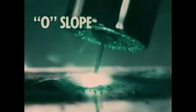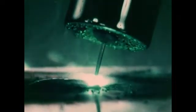Without control over the amount of current, the clearing of the short circuit as the wire touches the work is violent. An intense spatter occurs. The extreme heat is causing the remaining electrode wire to melt or ball up prior to the short circuiting or touching to the base metal. Note the arc reigniting with great rapidity. There is not enough time for a smooth transfer of molten metal. The entire action is literally out of control.